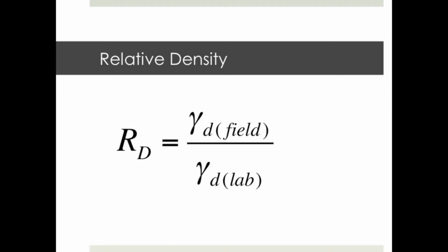Many job specifications will indicate structural fill has to be compacted to a certain degree. This is what they mean. If a roadway subgrade has to be compacted to 98% of its standard Proctor, then this equation should yield 98% or greater to meet specification. Also, moisture contents are normally specified. Specifications should indicate whether compacted fill can be within plus or minus 2% or plus or minus 3% of optimum moisture content.